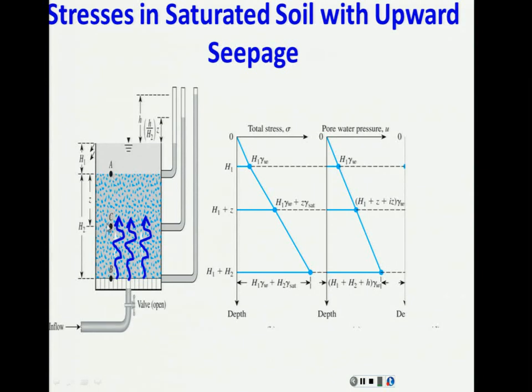Whatever you are in between is going to be a ratio between this H and the length that the soil is crossing, changing from a maximum here to a minimum here. That's why you have this H divided by H2 times Z, which is the depth. It's a ratio of this H.